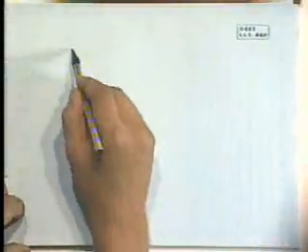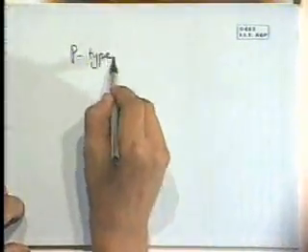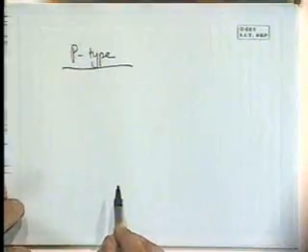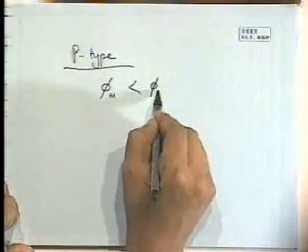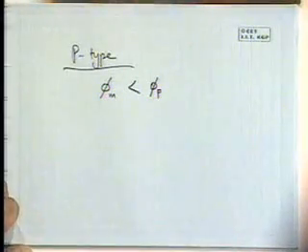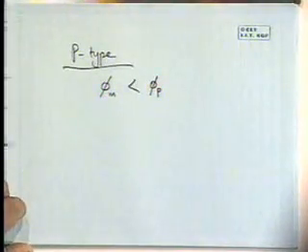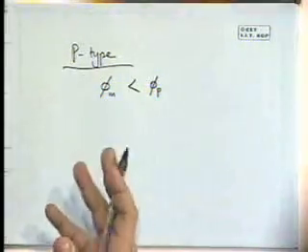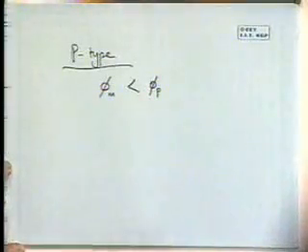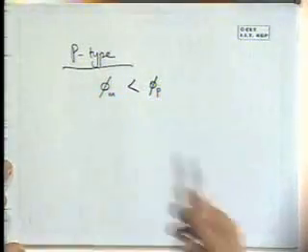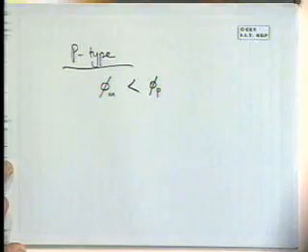The whole argument can be made for p-type also. In other words, for p-type, the Schottky can be created if phi m is less than phi p. In this case, we'll get the opposite. The holes will behave with this rectifying, same kind of behavior we'll see. Band will bend down. That's a barrier for the holes.